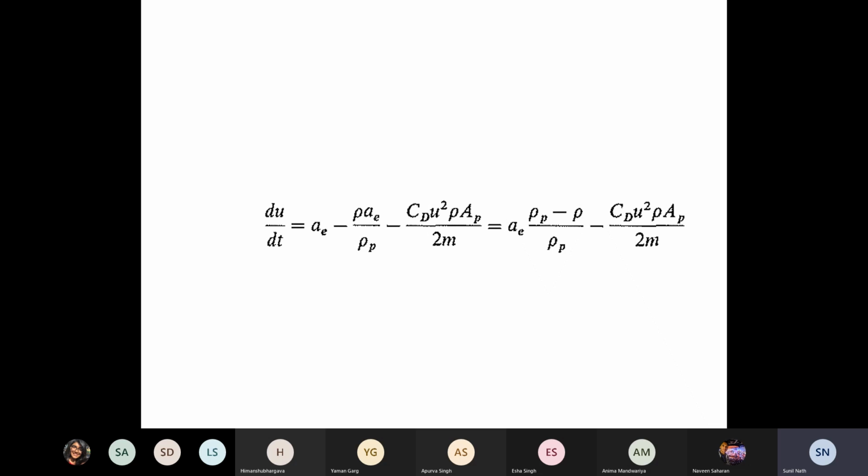So the centrifuge requires a little bit different analysis, but this expression is still valid within the assumption for the centrifuge of constant velocity, or du dt equal to 0. There is no assumption here about shape or about hydrodynamics. It is a general expression.